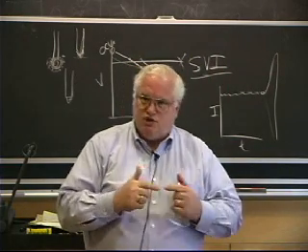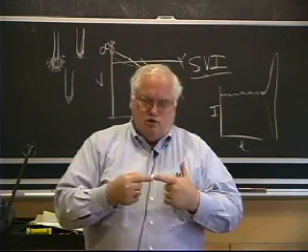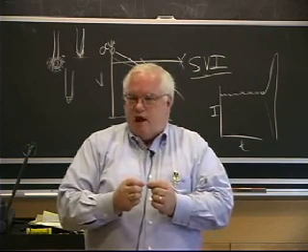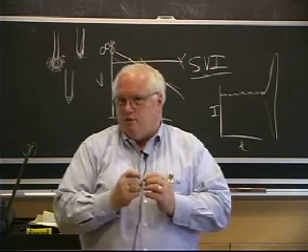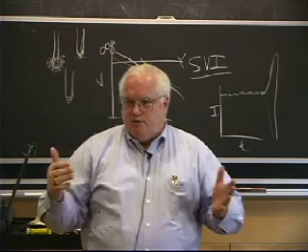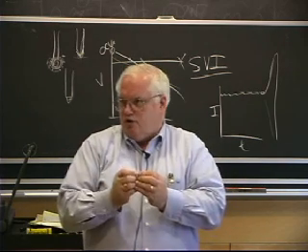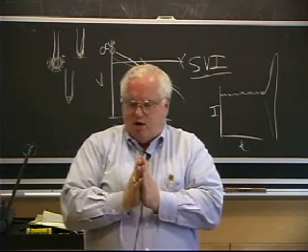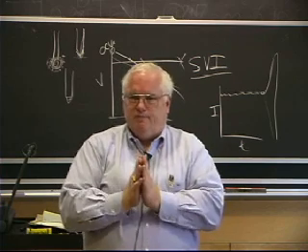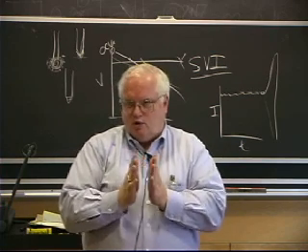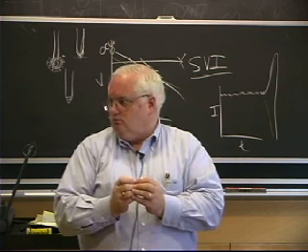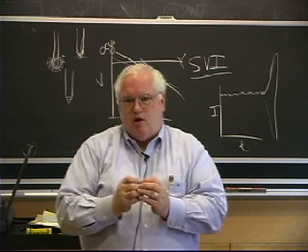So you can either use touch start, which is this type of stuff, or you can use the high frequency, 100 kilohertz overlay. Basically, you have a couple of little arc gaps if you go in the power supply down in the weld lab, and you have to adjust these and change them every now and then. If you're running 200 or 300 amps, you actually have the current going across this little arc gap within the power supply. If the power supply is water cooled, but most of them are air cooled, these gaps wear out. But you're basically allowing the arc to go across the gap.